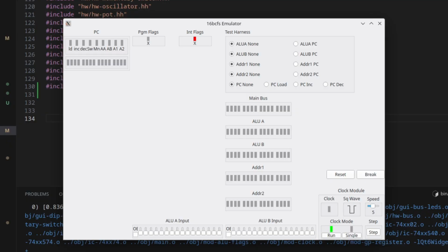Okay, I thought I'd start with something very trivial, and that is getting the X flag populated for both the program and the interrupt flags registers. Now, the X flag is going to be used to indicate context. It's not going to be visible to software, but I am definitely going to need to be able to use that in determining how to execute code. And so that's actually going to be feeding into the control logic for the control word lookup. All right, so the program flags has the X flag set to off or 0. The interrupt flags has the X flag set to 1 or high.